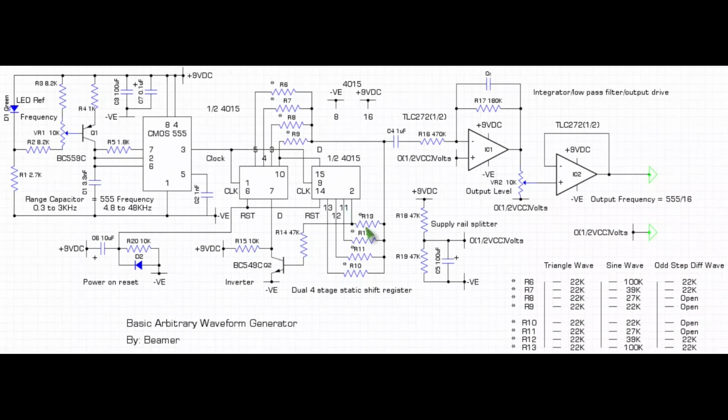So if you're going to make a connection, always make sure that there is a resistor in here and the value is not less than 22k. If you quickly look at the table here, you can see that it's either open or nothing less than 22k. So that is the business end, and that is how you program it.